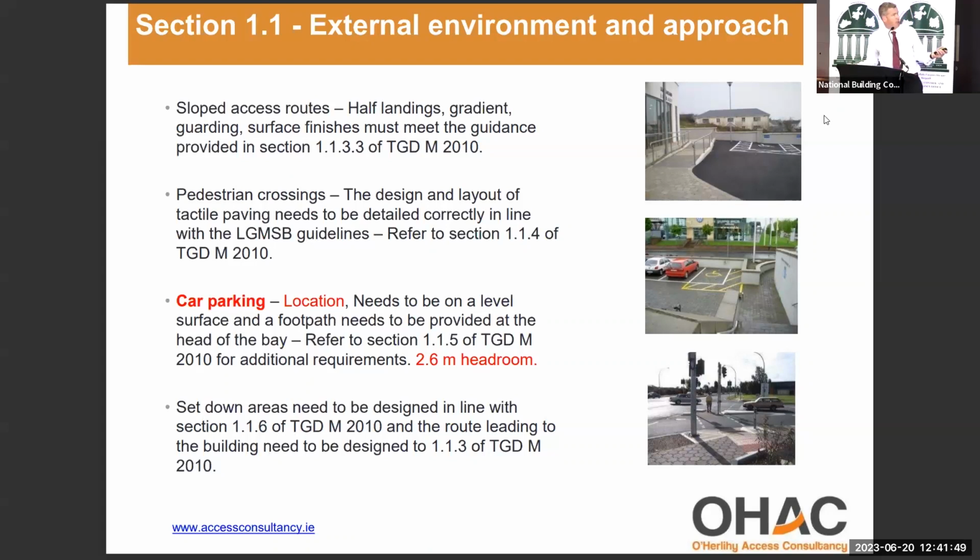In relation to car parking, it does say that the accessible car parking bays should be the closest space to the accessible entrance. So watch out for that when you're assessing your applications. And also when you're looking at basement car parks, there is a requirement that the clear headroom should be at least 2.6 meters from the entrance to the basement car park down to the accessible bays themselves.